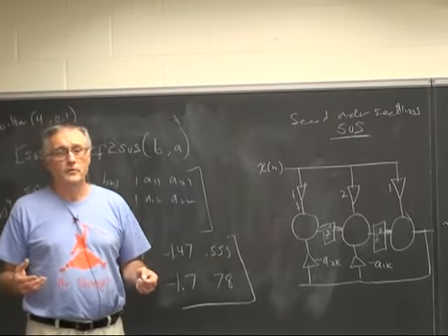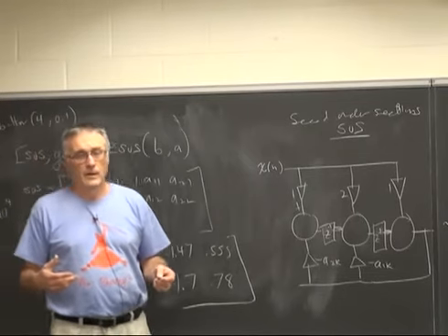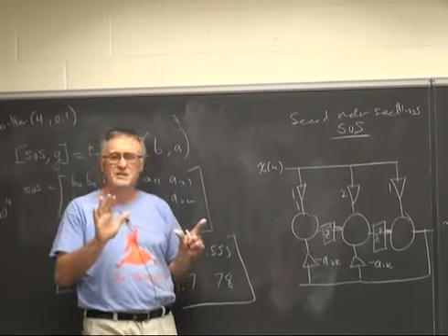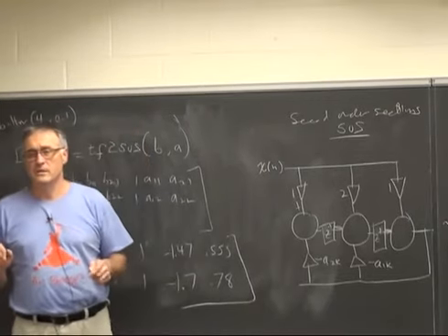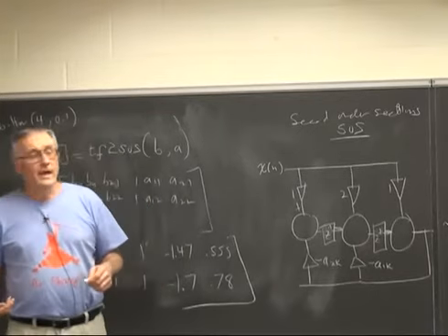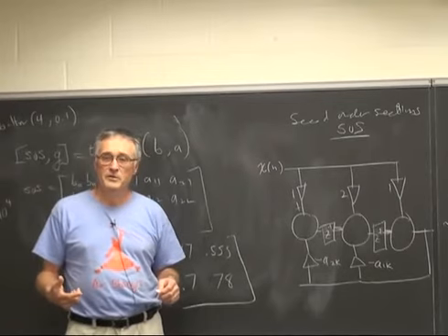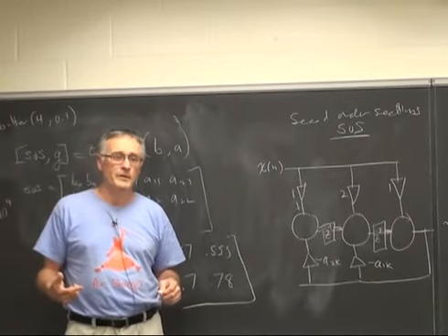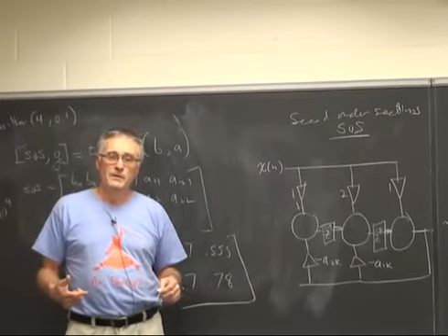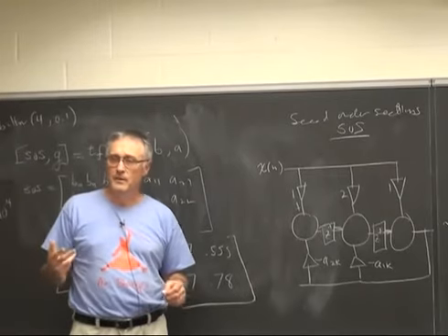You can show that for doing, say, an MPEG encoder, an MP4 encoder, you only need about 9 bits of mantissa. You don't need 24 bits of mantissa. So I implemented a 9-bit floating point, and one of the students last year to do Lab 4 implemented 18-bit floating point. So there's 9-bit, 18-bit, and 32-bit floating point available.